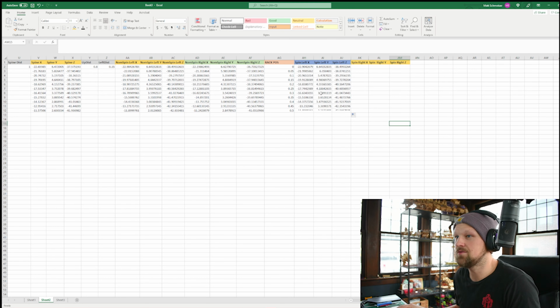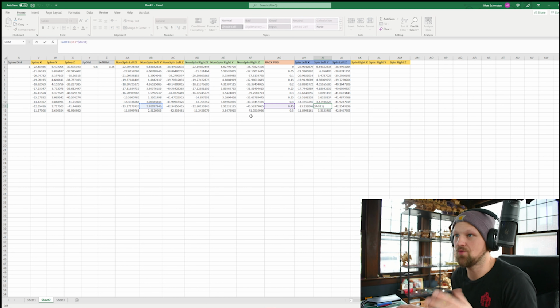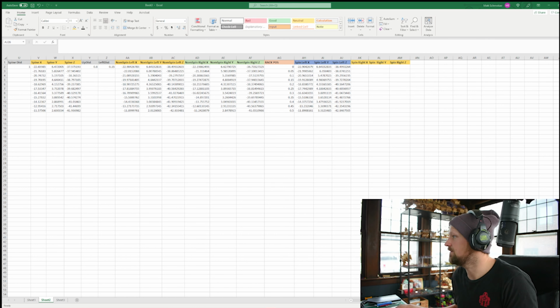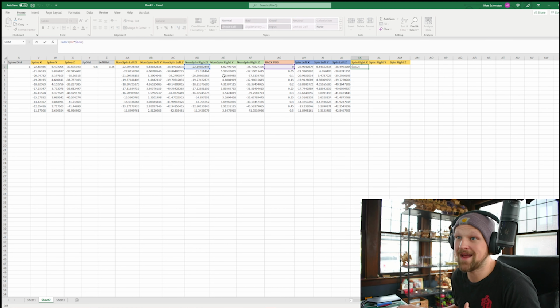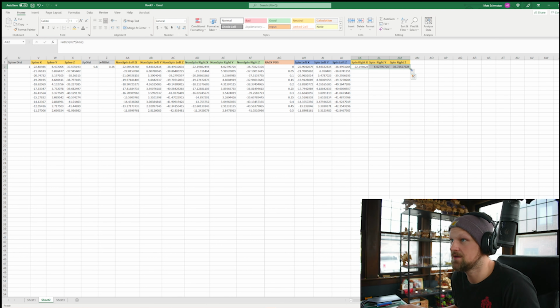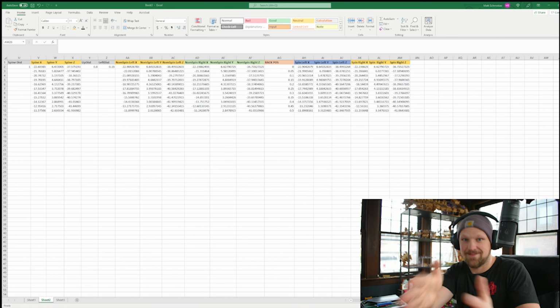Now the only unique thing here is, remember, the dollar sign doesn't go to the top because you're not following that variable. Your variable is changing. So if you even code it, you would have this be a variable that changes per whatever rotation you need. And then for the right, you do the same thing. Set up the same way, boom. Only now you're using the right rail as your nominal, and you're pretty much doing the same exact thing from that right rail. Bring it over and bring it down. And there you go. Very exciting.